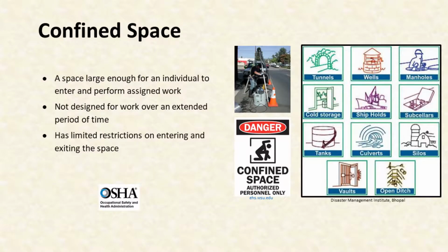One of the most dangerous hazards personnel may face is entering a confined space. Occasionally, while investigating manholes and catch basins, it may be necessary to enter a confined space. Some confined spaces require a permit to enter. It is important to know the differences between a confined space that requires a permit and those that do not, and the appropriate safety measures to take for each. Only authorized and trained personnel may enter a confined space.